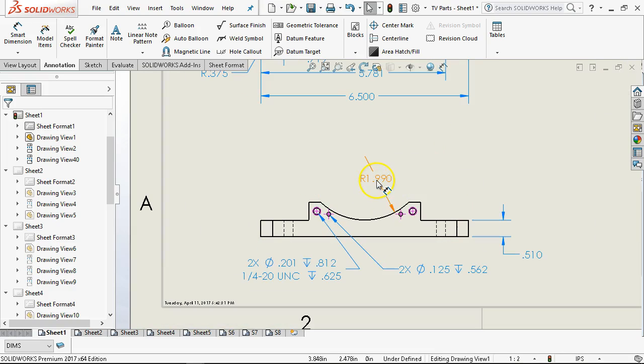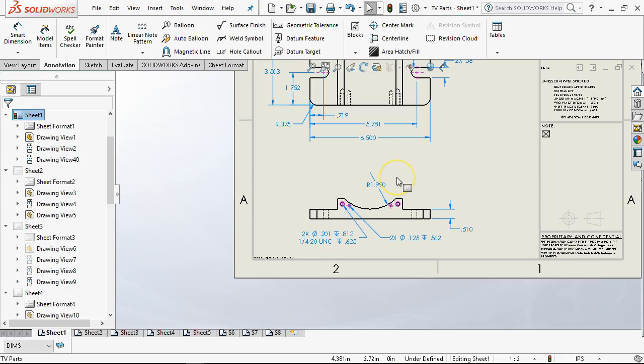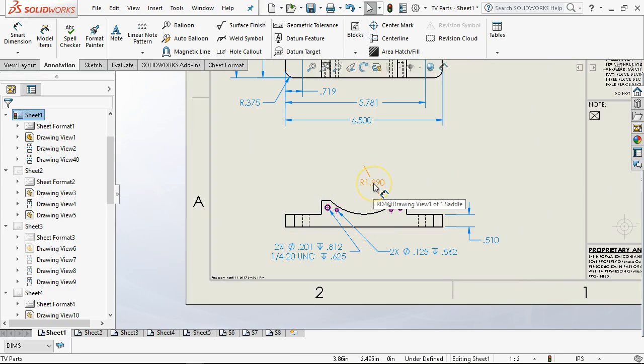All right, and the radius of 1.9, if we're roughing this out with a plus or minus 5, my worst case is I have 5 thousandths of material to remove. Or my other worst case, or my max min condition, says that based on this dimension, I have 15 thousandths of material to remove. If that's acceptable, we go on.